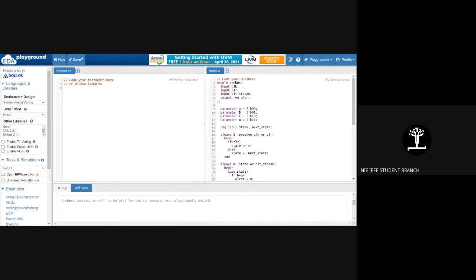So just look at the chat, guys. I'll just tell you verbally how the test bench is working. If anybody forgot from yesterday, all inputs are reg type and all outputs are wire type. And then you can see the word called UUT. That's when I'm instantiating my module. UUT you can name anything, or you can name it Skanda or your own name. It doesn't matter. UUT stands for unit under test.